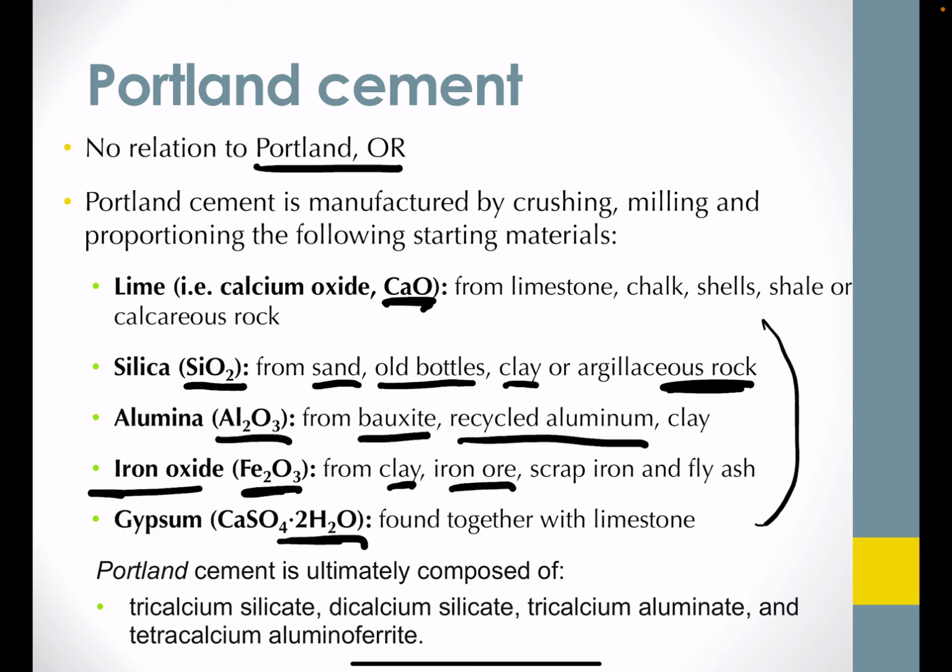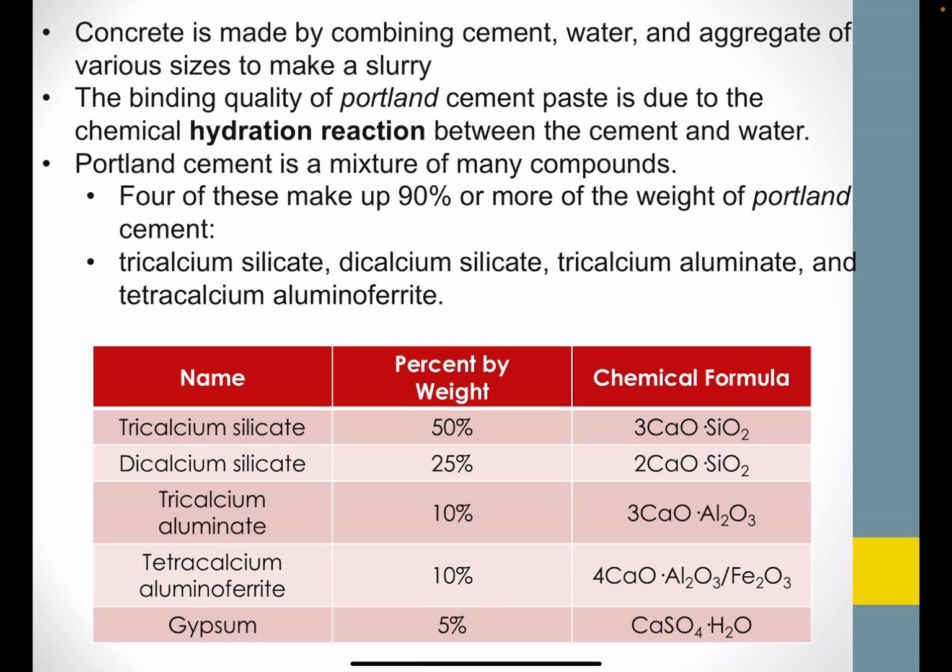Portland cement, when on its way to being set, is known to therefore take these starting materials and generate tricalcium silicate, dicalcium silicate, and even tricalcium aluminate, and the version there that includes the iron material. So that is the tetracalcium aluminoferrite that can include that final iron oxide component.